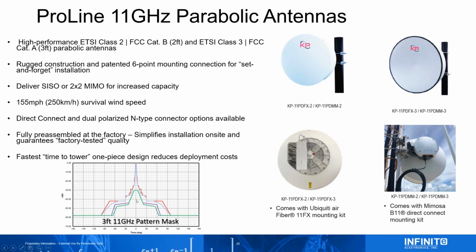And here's just a sample mask. The side lobes on this are just outstanding. You're meeting your Cat B compliance for the 2-foot, and then the Cat A for the 3-foot, and then ETSI Class 3 if any of you guys are in Europe on the 3-foot, and Class 2 on the 2-foot.